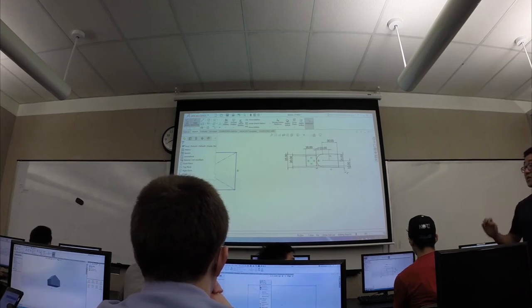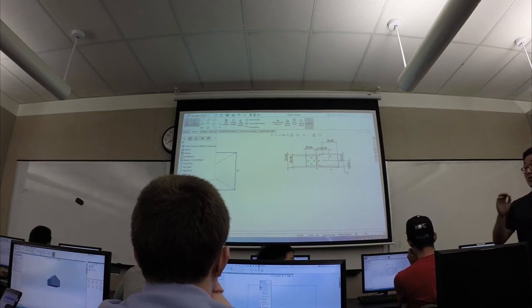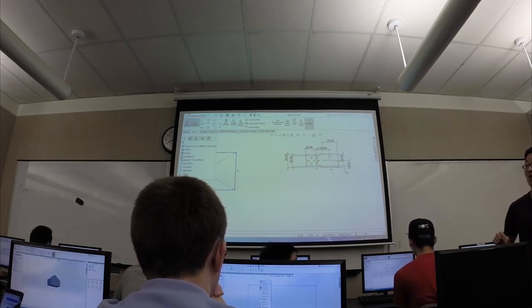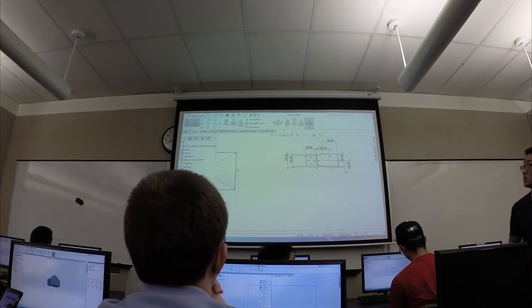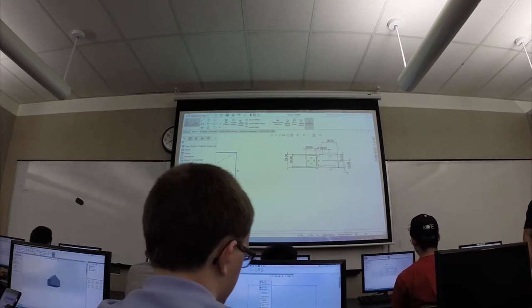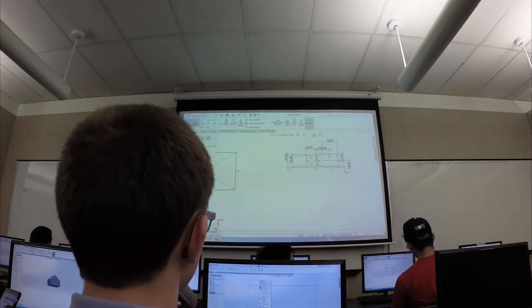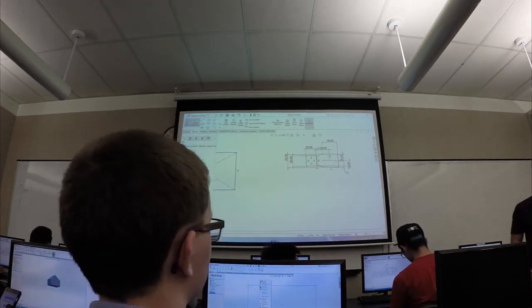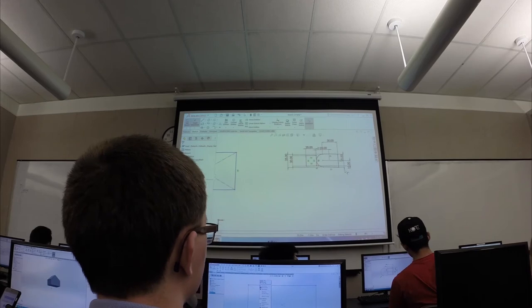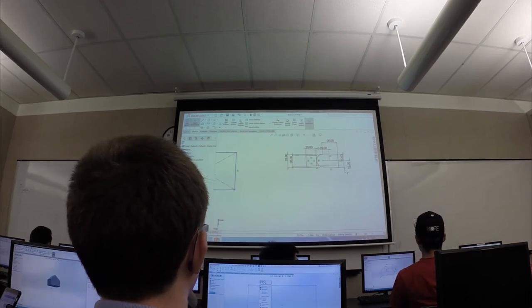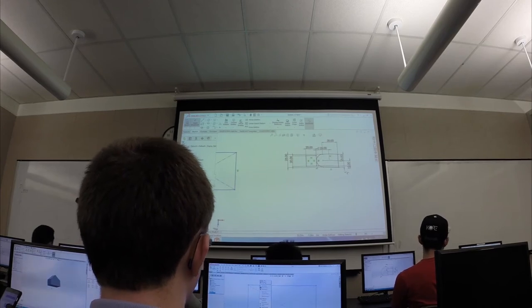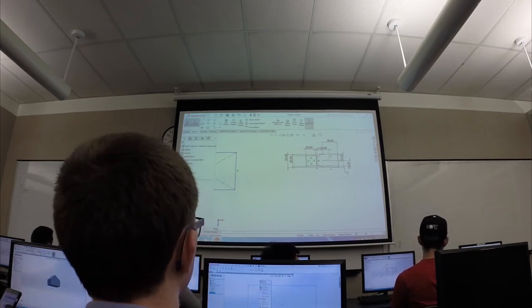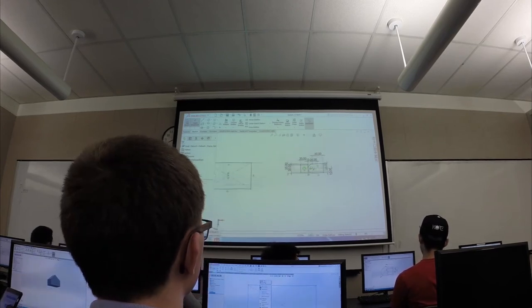Especially as you start to make certain edits, as soon as you change one thing, something that's not defined will also move along with it, and then your part can change drastically in ways you don't want it to. So always remember, whenever you have a sketch, try to fully define it as much as you can. It's a little time consuming sometimes, but in the long run, it'll return its investment. Doubles and even more.